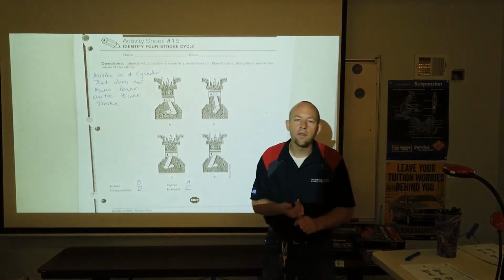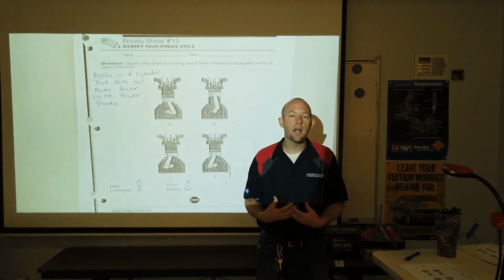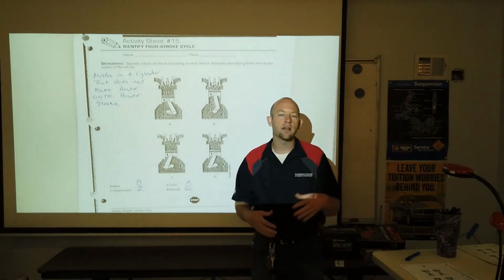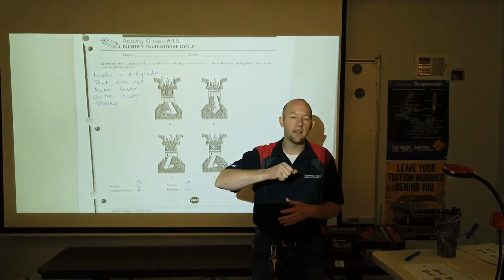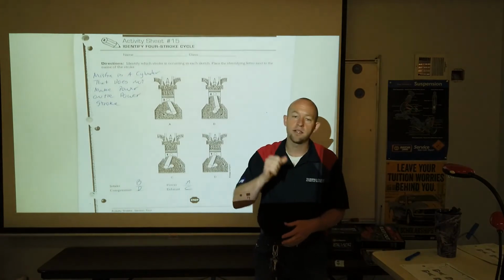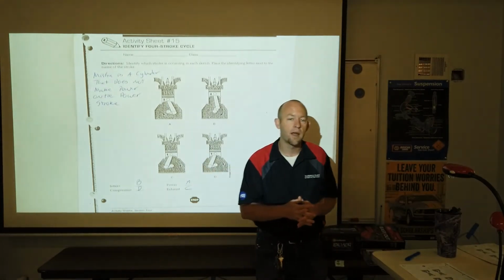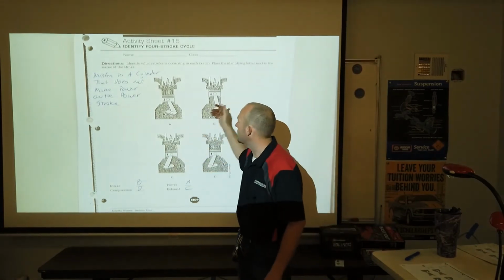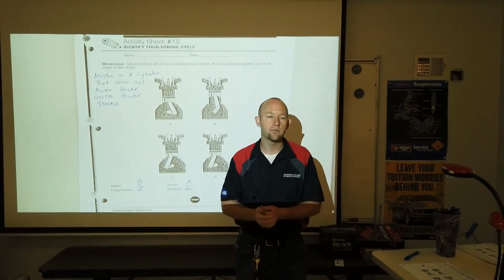Now, on the intake stroke, I'm supposed to be pulling in an air fuel mixture. But if I don't have any fuel, if no fuel is sprayed by that injector or something along those lines, then I just pull in air, I compress air, I try to light it, and there's nothing to light. Therefore, I have a misfire that affects my power stroke again. But that's something that relates to the job of my intake stroke. My intake stroke is supposed to pull in an air fuel mixture, all right?